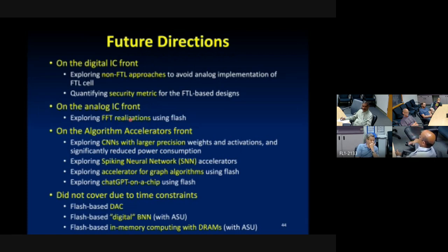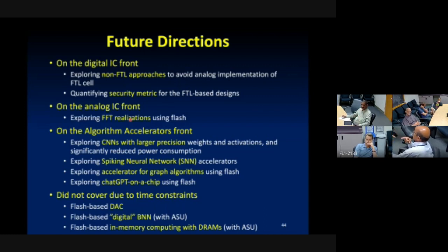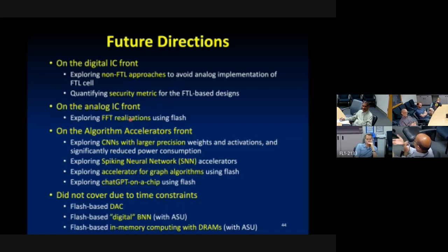ChatGPT, I couldn't do training, I could only do inference. And why is that? One key reason is that training needs you to overwrite weights. My weights are stored in Flash. And what I didn't mention is Flash is quick to read, but to program, remember, we have to apply these pulses and we have to do this iteratively. So programming takes a while. Programming in a Flash memory takes in the microseconds, which is glacially slow. So for VLSI, it's very, very slow. So programming is not something I can do.